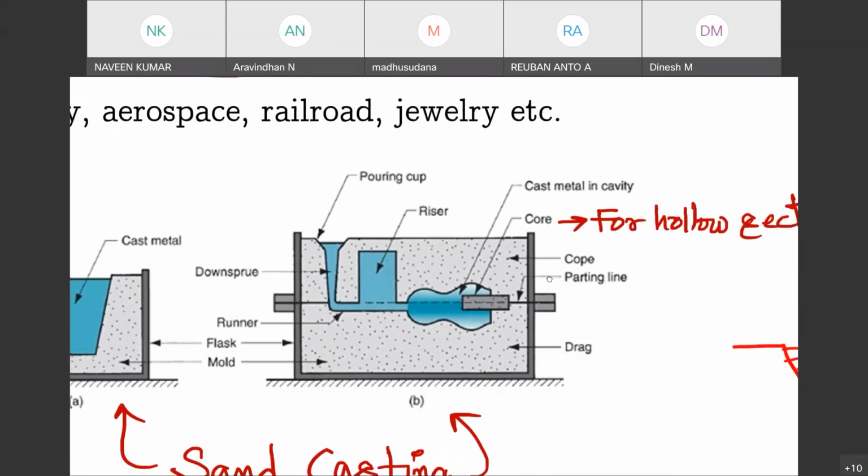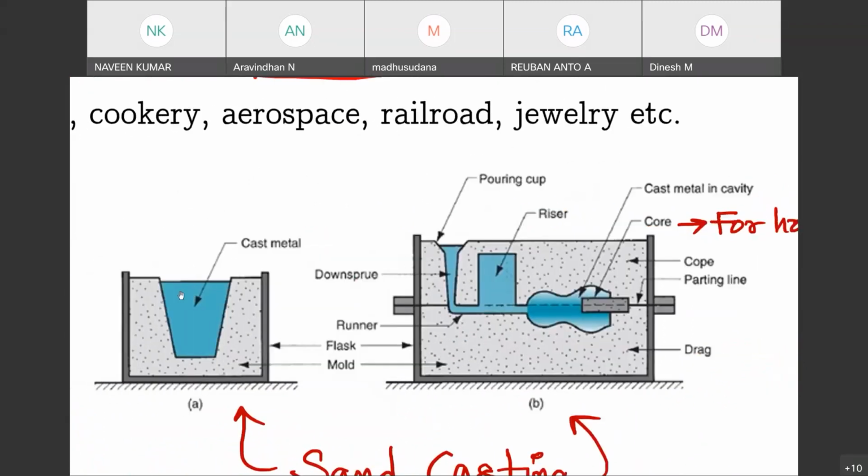So you can't handle it directly, and you can't directly pour it also, because if you're directly pouring, it might spill here and there. It might disturb the geometry itself, because you don't want to pour with huge velocities, right? You can't open a tap and directly pour it, because it will disturb the geometry, because you made this hollow cavity for some purpose, so that after solidifying it, I get a desired shape, right?